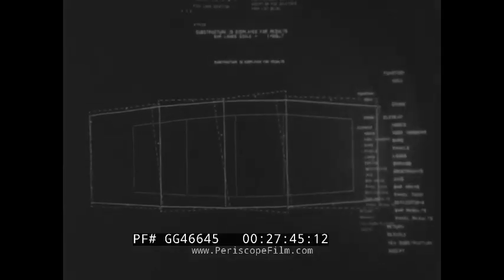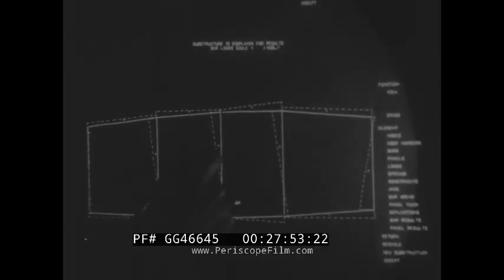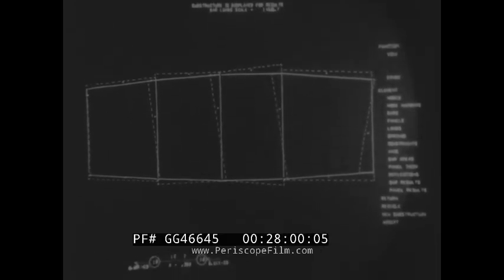Returning to a display of the rib, we can look at the bar results to view a plot of the bar loads in the rib. We can also display the loads in an individual bar for up to 8 bars. This yields exact load information for the bars.